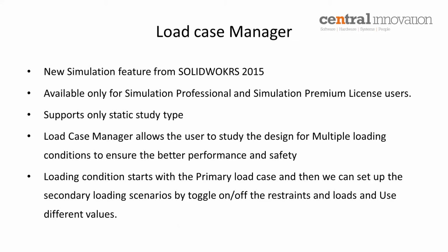Okay, the first thing is Load Case Manager. If any of you are using SolidWorks 2014 or previous versions, Load Case Manager is not available before 2015. So Load Case Manager is a new feature which is available from SolidWorks 2015 version onwards. And as I said before, this feature is available only for Simulation Professional and Simulation Premium license users.